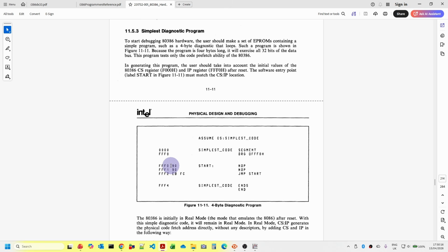Now, the reason I have upgraded the test board here to have 4 bytes worth of data is so I can actually try this. So what I'm going to do now is set these bytes on the data bus, and reset the processor again and see whether or not it just goes round in circles. This should mean it will go from the very top of memory at FFF0, go all the way up to here, and then bang it around again.